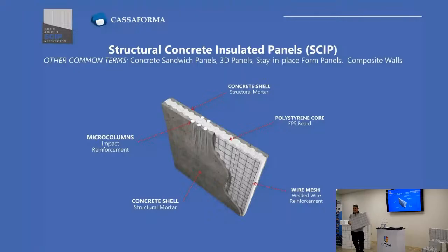It's up to the capacity of the mortar, and that is out of our hands for the calculation. The only thing that is related to that is that, of course, every time I get more height, it will increase the wind load pressure. So it might be a possibility that we have to switch panels according to that. But usually, if there's no implication about the winds, the same panel that you use for a one-story home will be used for a three-story or four-story home.